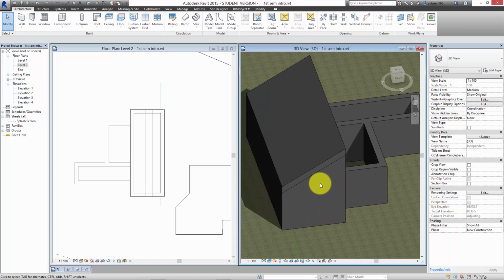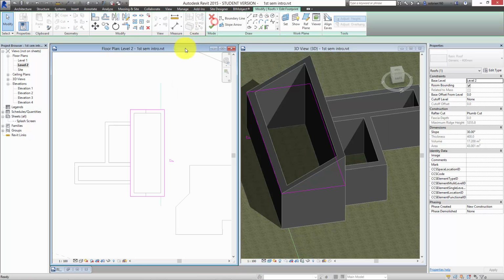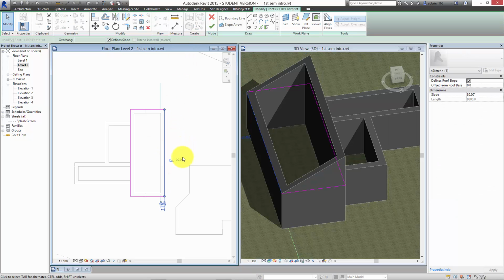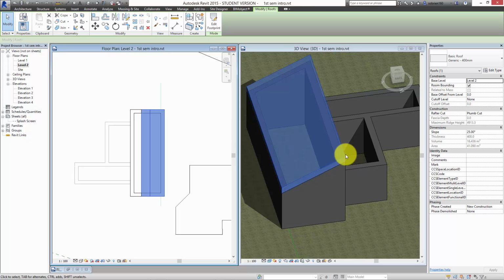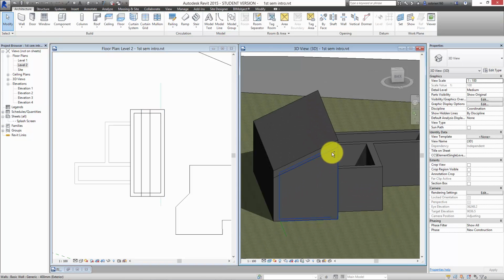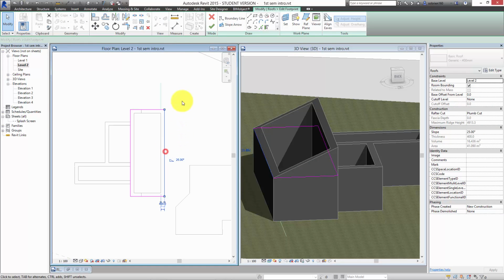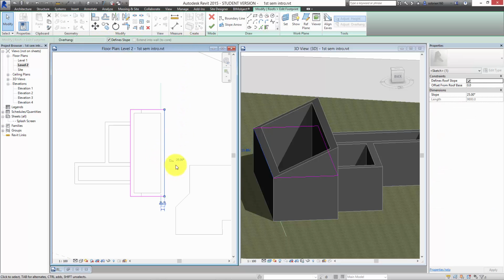And once again, this is a time saver, because that allows me to go in here, select the roof again, edit the footprint, select the slope. I can change it from a 30-degree slope to a 25-degree slope, for example, and accept it. It changes the slope, but it also changes the walls so that they follow the orientation of it. So let's just do that so it makes an intense difference. So edit footprint, select this, change the slope.